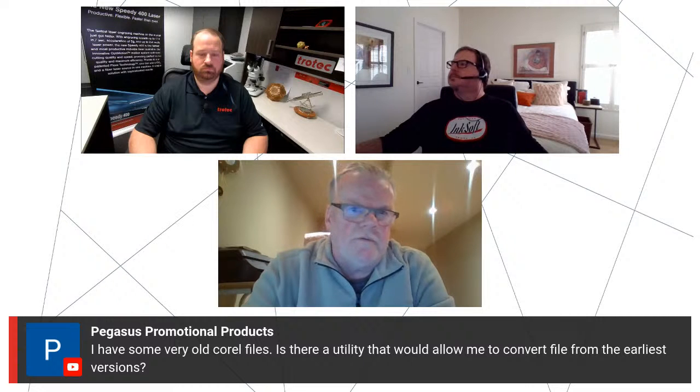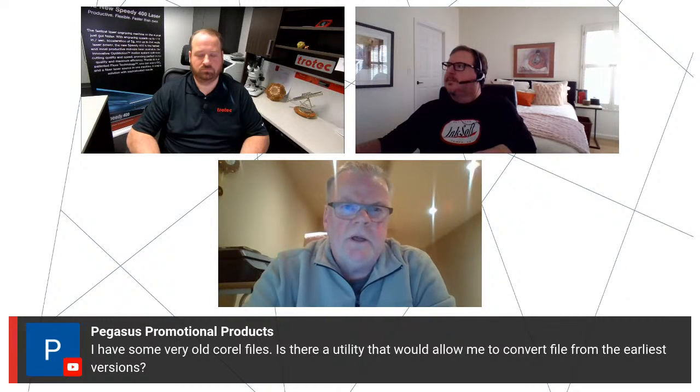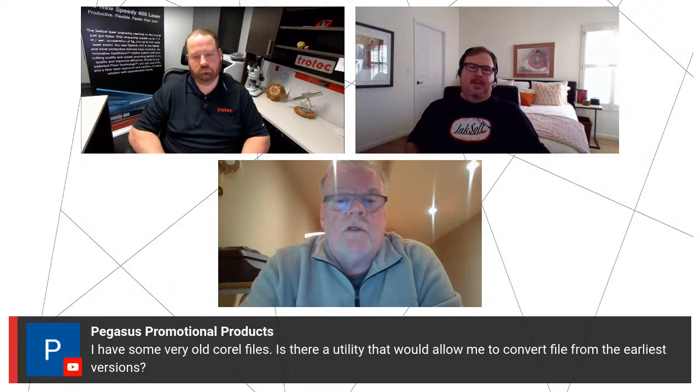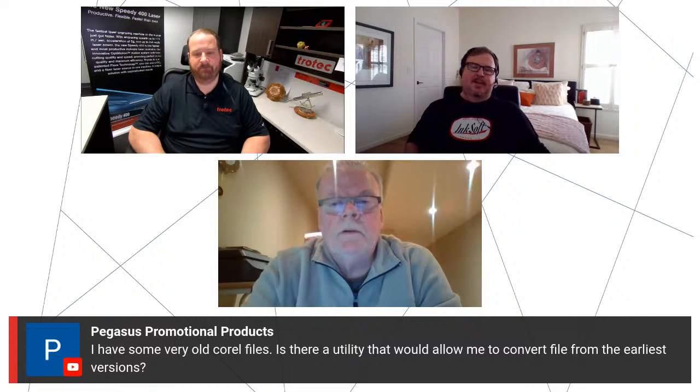The only issue with mass conversion is files that have text in them. You'd want to make sure that you have the fonts, or you can settle with the fact that the text may appear differently once they've been converted. From my experience, CorelX7 is the magic version that converts all the old files, and we have a batch conversion utility on that that'll bulk convert them. I'd have to dig around to see if I could find it, but that's built into Smart Designer.